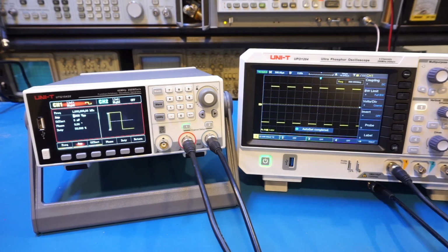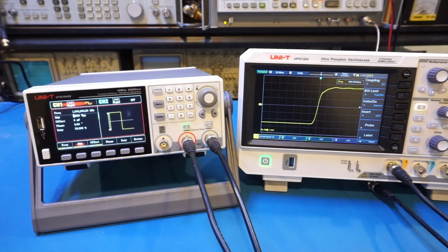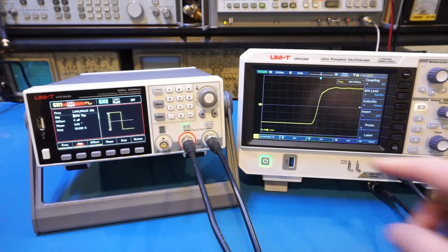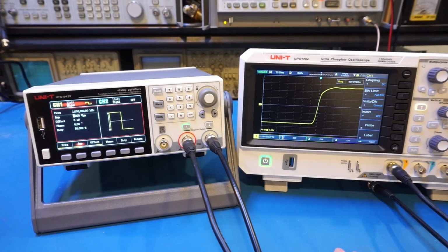And of course, let's acquire the signal. So let's actually expand the horizontal scale a little bit so that we can see the waveform a little bit more clearly. This is our slew rate. And you can see right now we're at 25 nanoseconds per division. And this is definitely not the steepest that I have seen. And if I remember, on the 962E, the slew rate is independent of the frequency. So let's actually verify that here.